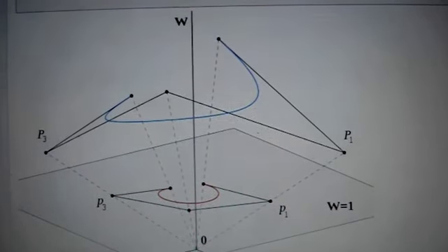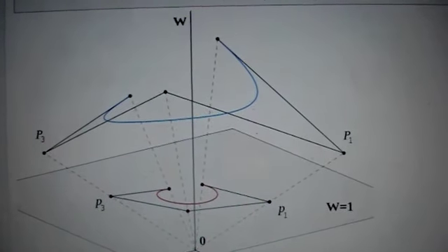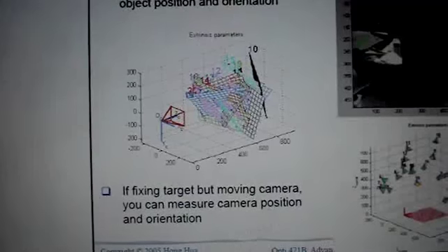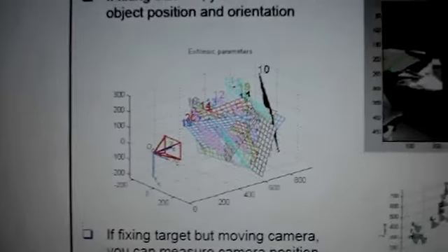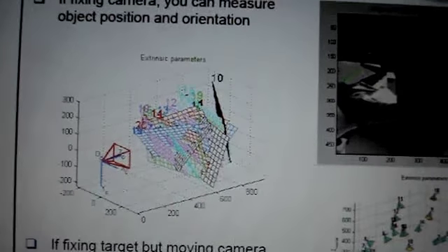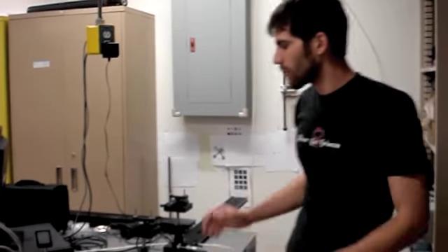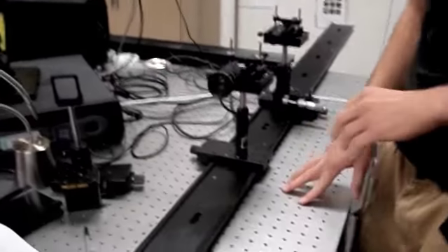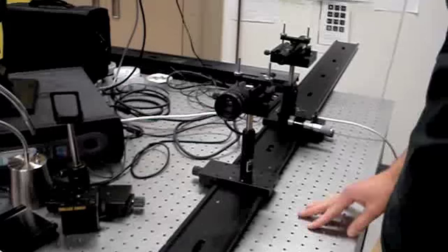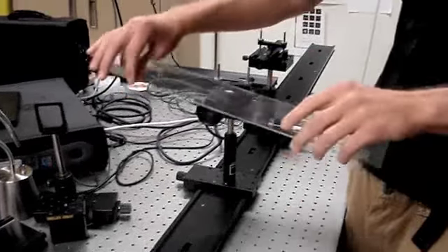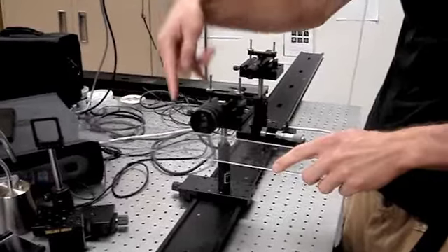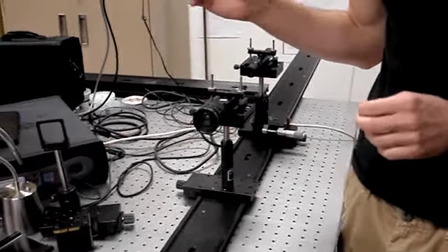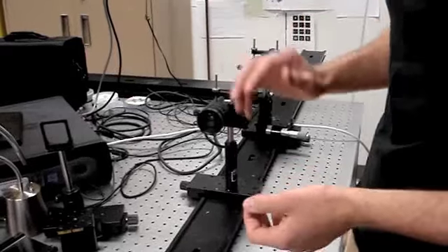So our MATLAB code uses homogeneous coordinates and linear algebra to create a system of our different images and project them into 3D space. For our normal lens system, we wanted to know more about the details of it. So we measured the field of view by imaging a ruler, measuring how far away that is, and putting that on the screen. From that, we determined that in width, our field of view is about 32 degrees, and in height, it's about 24 degrees.